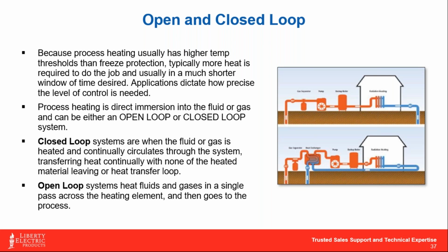Okay, so generally closed loop systems are way more effective at reducing the size of the heater needed, because again, we can recirculate fluid and keep adding to it each time, versus an open loop system where if you have to do a 30 to 50 degree temperature rise on some water going through it, you're going to need a big heater or a very slow flow rate to achieve that type of temperature rise in a very short amount of time.